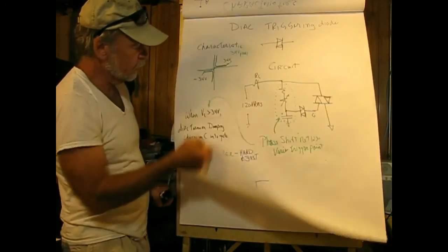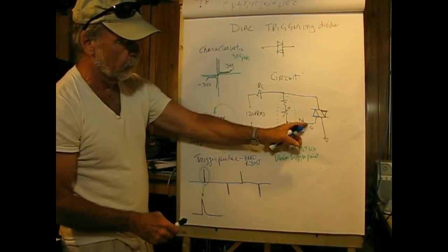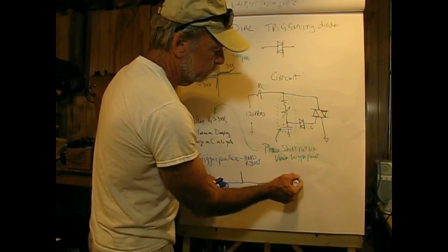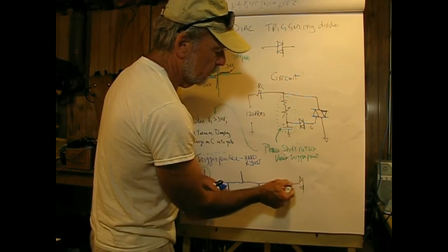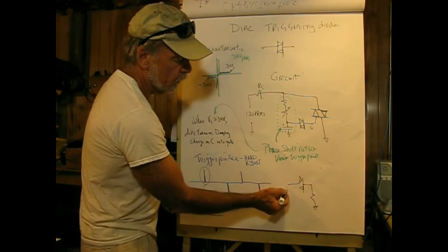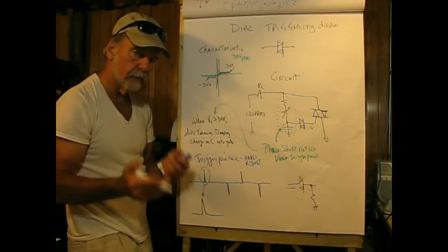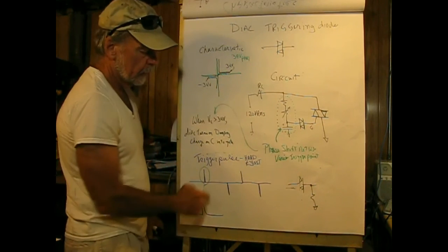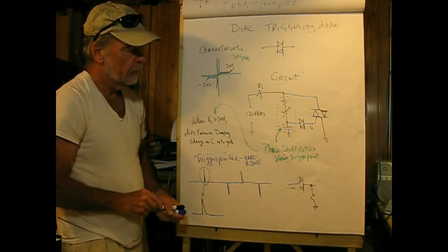So we'll be seeing this in lab, and actually be building a little circuit to take a look at what happens here. And that circuit would have the diac feeding a resistor to ground. So when C discharges, we're able to pick up what that looks like as the voltage drop from this resistor to ground. And you should be seeing something like this, which is really pretty impressive.